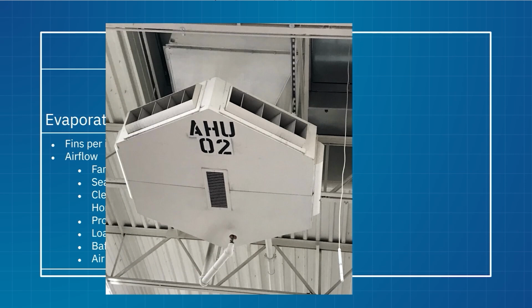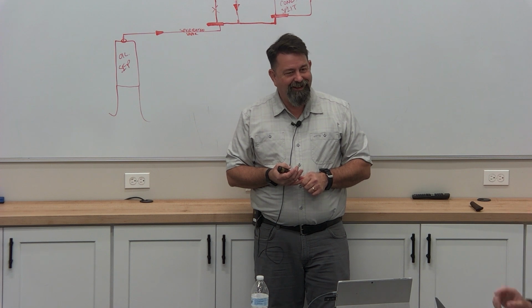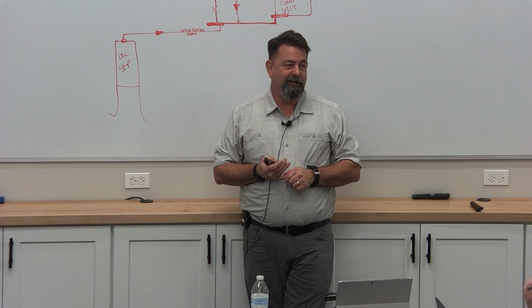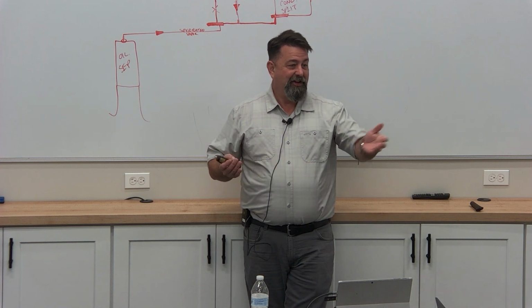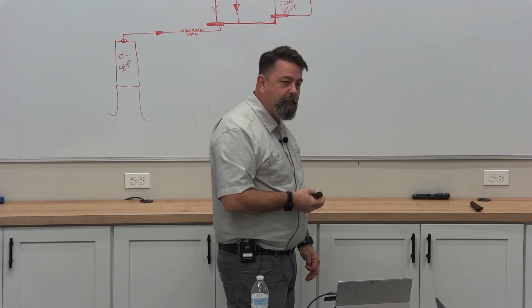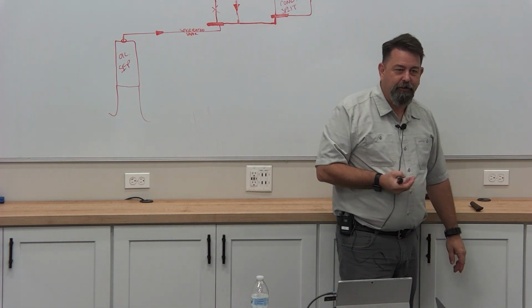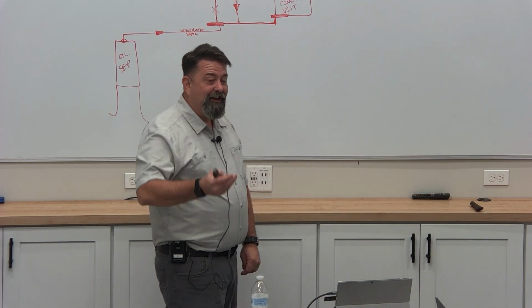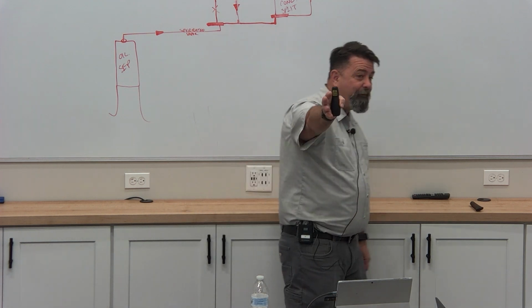How many grills have I got? One. How many supply grills are on this duct pack? Six, if it's a hexagon. It is a hexagon, you're looking at it. All right. How many CFM per grill? Divide that 6,000 by 6. So we're close to 1,000 CFM, 6,000 CFM unit, 6 grills. That's 1,000 CFM. That checks out.